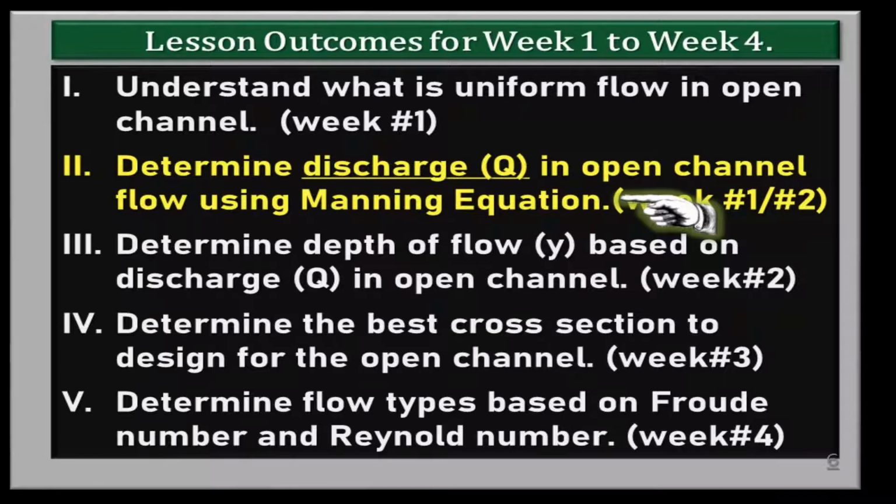Lesson outcome number 2. Able to determine discharge Q in open channel flow using Manning equation. So, you have to understand what is Manning equation and understand all variables related to the equation. Lesson outcome number 3. Able to determine depth of flow Y based on discharge Q in open channel. Depth Y is one of the variable in Manning equation. You have to do trial and error approach to get the depth.